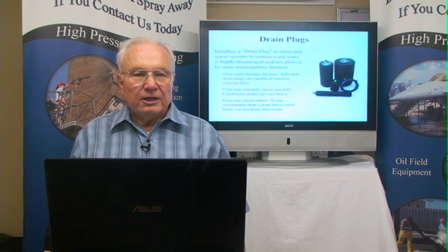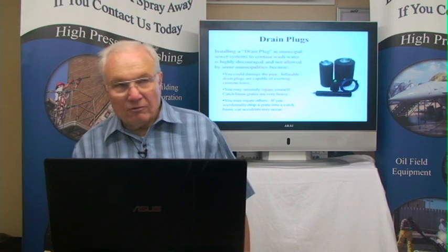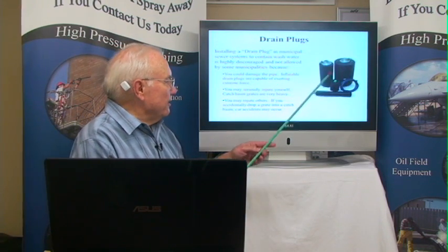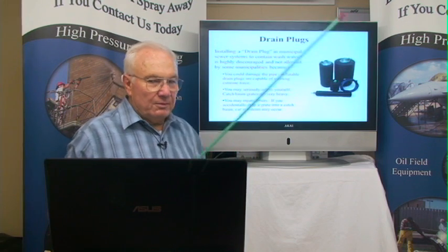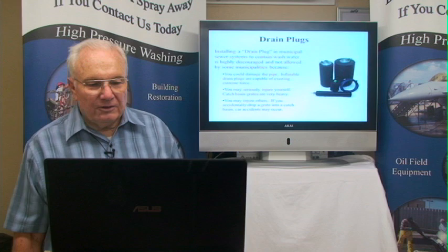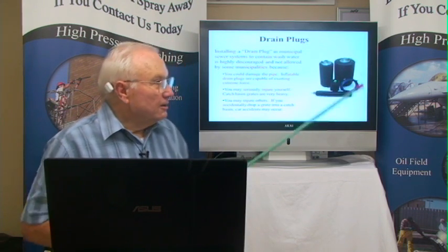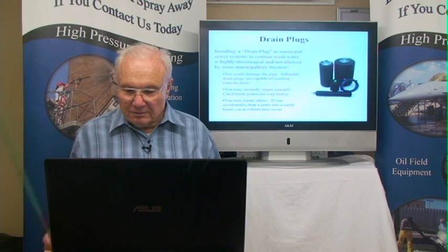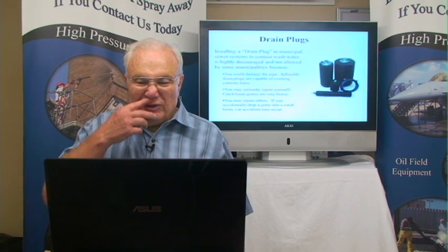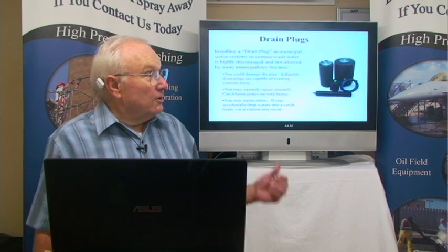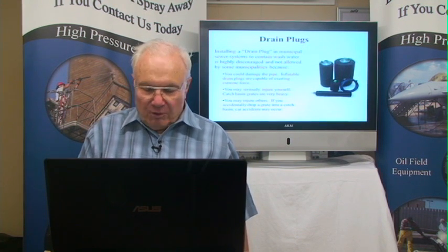Installing drain plugs in a municipal sewer system to contain wastewater is highly discouraged. The reason why is for these to work, you put air in them. We've had several situations where the contractor's personnel put too much air in them and blew up the storm drain system, or to keep the water from going down in there. So if you use these, there's a risk. And the risk is you might be repairing a municipal storm sewer system because you put too much air down there. I want you to bring those to their attention so at least you were aware of that particular product.